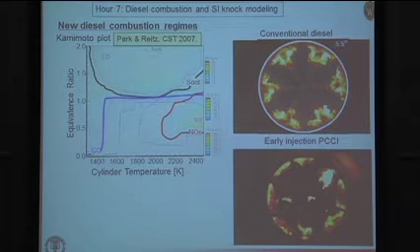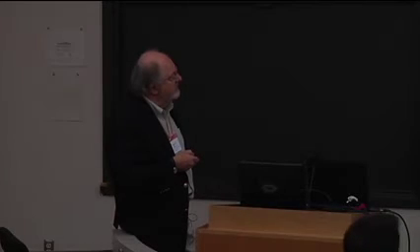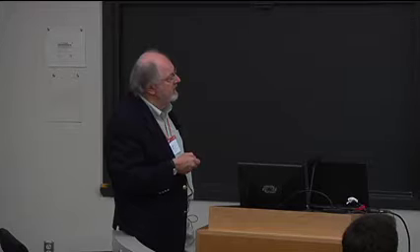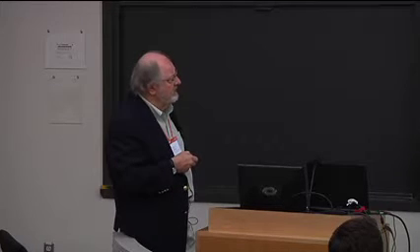And what you can do by doing that type of calculation, using a CFD code or Chemkin or such a code that also includes a soot model, is create these sort of islands where, for example, at high temperatures and low equivalence ratios, you find a lot of NOx is being produced, whereas with high equivalence ratios, with very rich mixtures, a lot of soot is produced. And then with very lean mixtures and low temperatures, you find unburned hydrocarbons and CO.